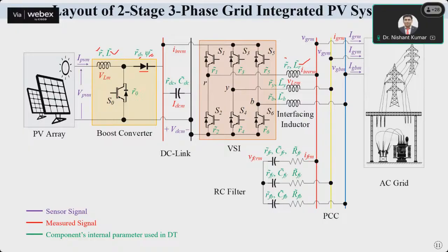Similarly, this is a switch. A switch has an internal resistance. A switch actually has two types of losses: the switching loss and the conduction loss, and these are two different things. Whenever it triggers, you will see a certain amount of loss, and then once the system is running continuously for a certain duration, you face certain other losses. Those are these two things. That's why we should consider two resistances here. Similarly for the switches. That is how generalized you can be in building the model.